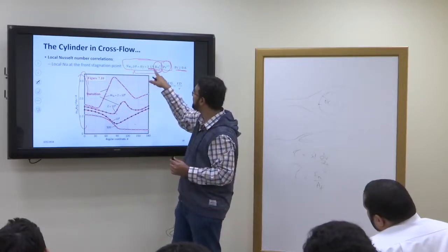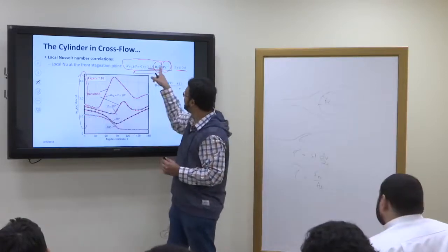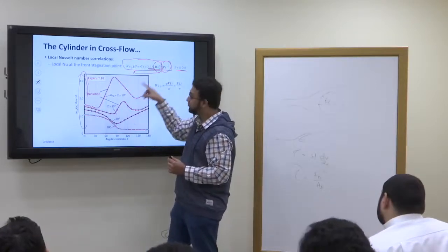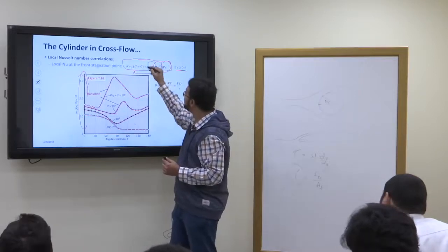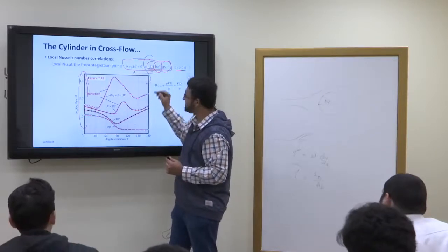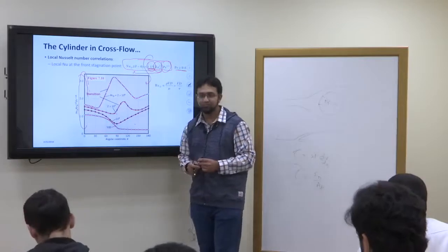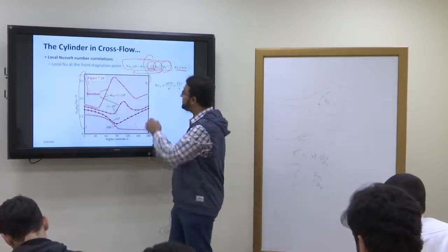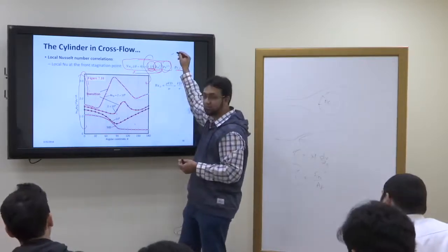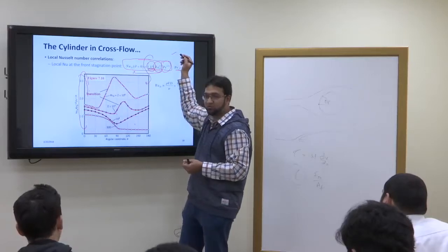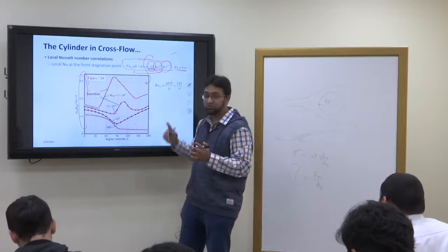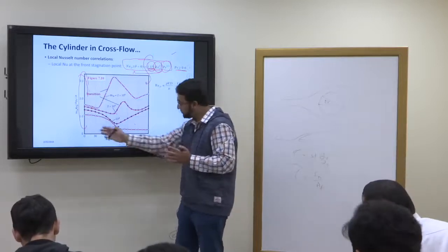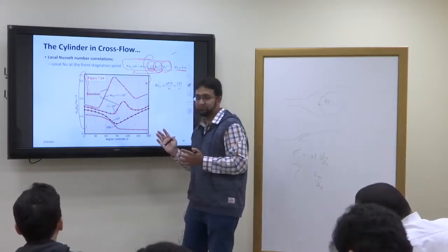So it's Nusselt number into Reynolds number power -1/2 into Prandtl number power -1/3, and this coefficient is represented in these graphs. So when theta is 0, you have this formula, and the coefficient is 1.15 when theta is 0. But when theta is not 0, then use the graph.